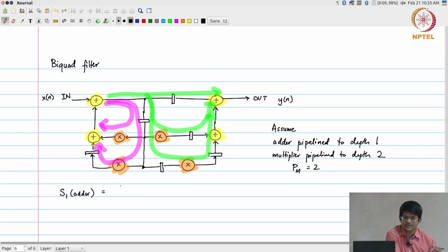Similarly, 4 multiplication operations, I can finish those within 4 clock cycles, 4 phases. So, I will start off with the assumption that n is equal to 4. If it turns out that it is not going to work, I will probably have to change it and use a larger value of n. With that choice, n is equal to 4, I have the ability to schedule 4 different units across 4 phases of time, okay. I am going to call the operations themselves, I will just label all of them. This is A1, A2, A3, A4, M1, M2, M3, M4, okay.